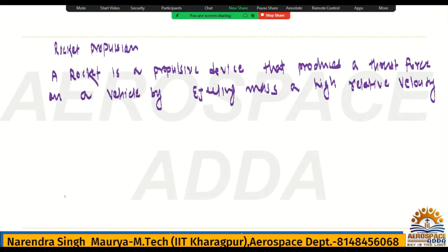It is very nominal at 10 to 15 Mach for the rocket engine, but the maximum Mach number possible for the jet engine or air breathing engine is 5. For the air breathing engine, the rate of climb decreases with altitude, but in the case of the rocket engine, the rate of climb increases with altitude. These are the basic differences, and you can analyze many more, but these are the major differences between the air breathing engine and the rocket engine.